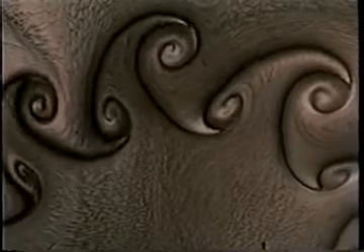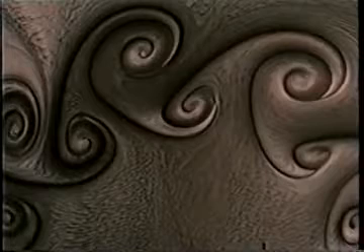As we have seen, a steady flow may become unsteady for certain ranges of flow parameters. The instability takes its energy from the mean flow, and the mechanism can be thought of as a selective amplifier, its characteristics governed by flow parameters. Flow instabilities occur everywhere,